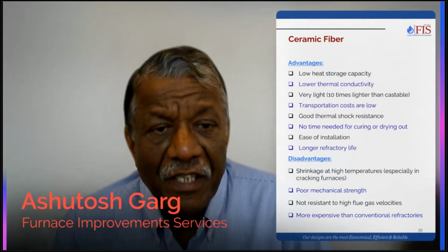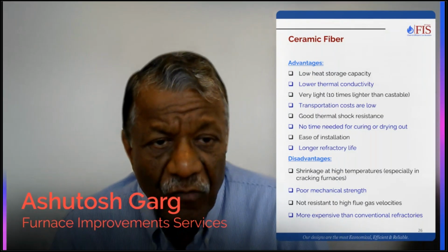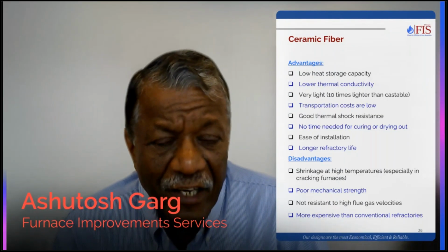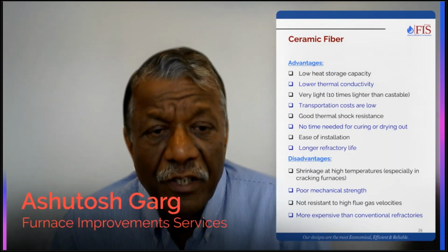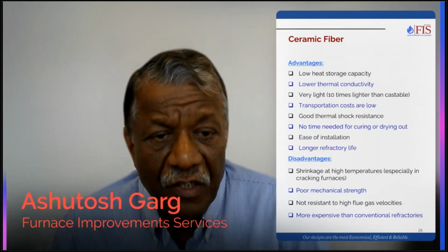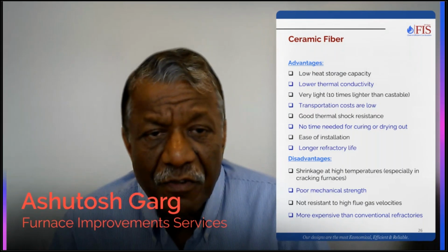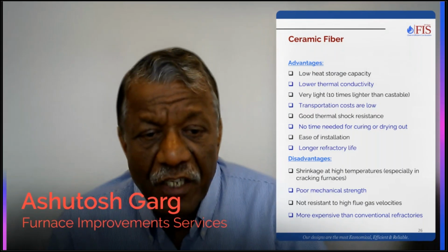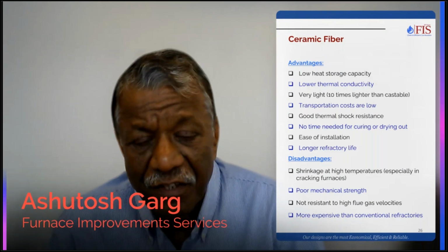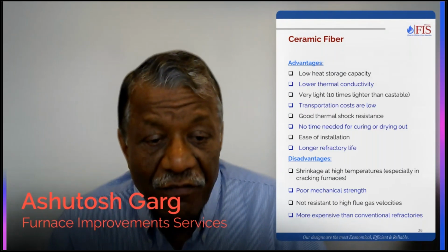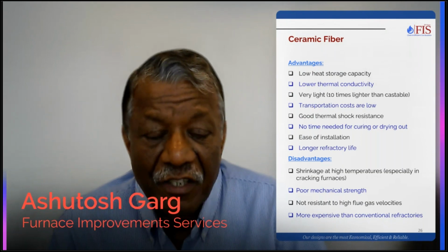So these are some of the advantages of ceramic fiber. As I said, low heat storage, lower thermal conductivity, very light. Transportation cost is low, no damage during transit. You don't need to cure it or dry it out. So these are some of the advantages. The disadvantages, especially shrinkage at high temperature. That's why we don't prefer it in cracking furnaces. Not resistant to high flue gas velocities, and sometimes they could be more expensive than conventional refractories.